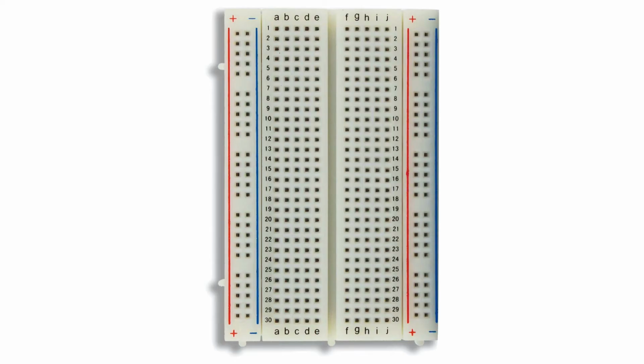The other thing in this lab I want to talk about for a moment is the breadboard. Now the breadboard is used instead of soldering because it's easier to experiment with, to prototype, to try things out. And again, you don't have to worry about burning yourself on a hot soldering iron. At first, the breadboard might seem a little intimidating. I know it did for me. But I'm going to explain it, and you'll see that really all the breadboard is an extension of wires.